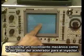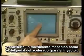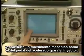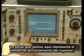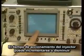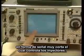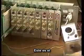Now it gives us a signal that converts the mechanical pedal, the driving pedal, the gas pedal, to the injector. This signal right here represents the on time of the injector. You'll notice that the on time can increase and decrease, and it's a very sharp, very nice pulse that controls the injectors.